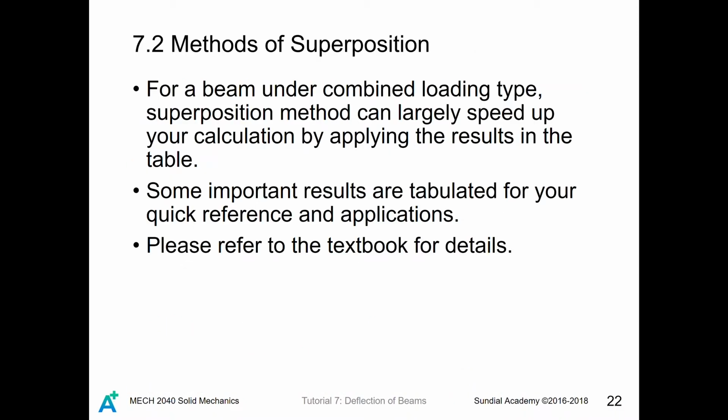Next, let's talk about the method of superposition, which is a great way to simplify the problem-solving process by using the table lookup technique. This technique is particularly useful when you are analyzing a beam with a lot of loads, because for many loads you could write a very, very long moment equation.